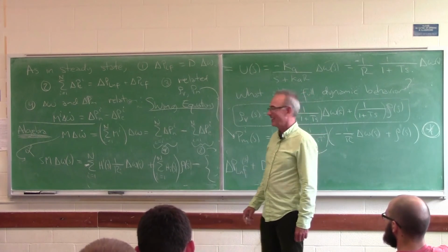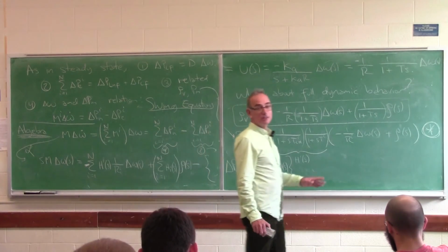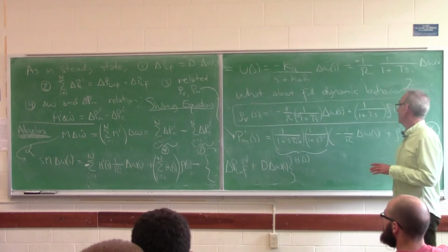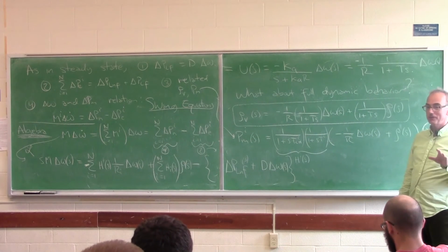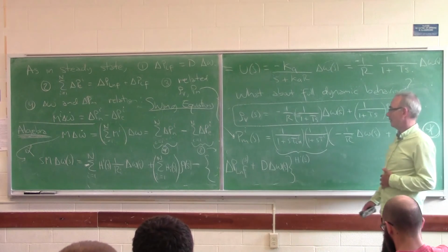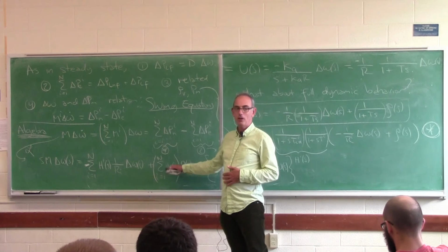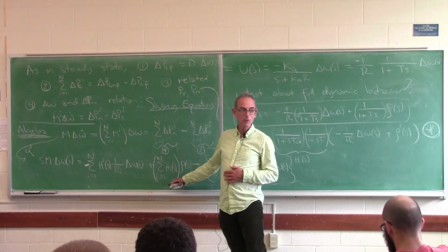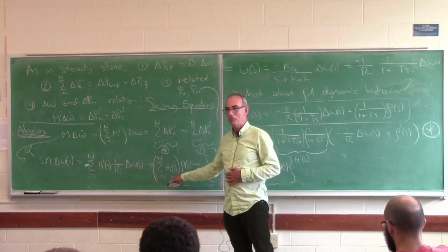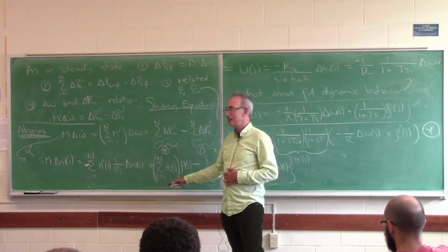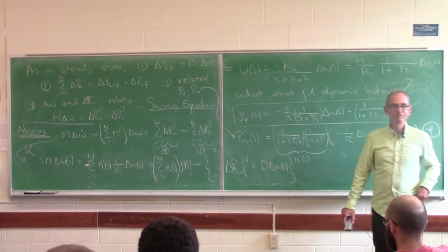Now this looks awful, doesn't it? But at least this is all designed, remember. Generators are mandated to set up certain droop gain parameters, and it's done in such a way that this is not so bad. You know what I mean? That all the pole locations are not that far apart, things like that. So this thing turns out to not be bad by design. All right, so I can kill this, can't I? Excuse my language.